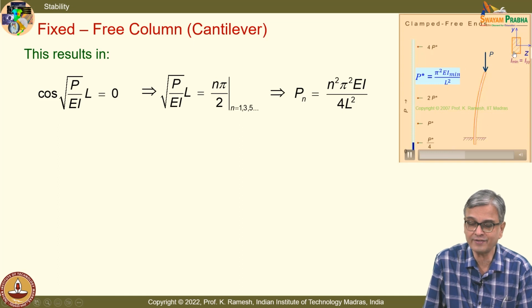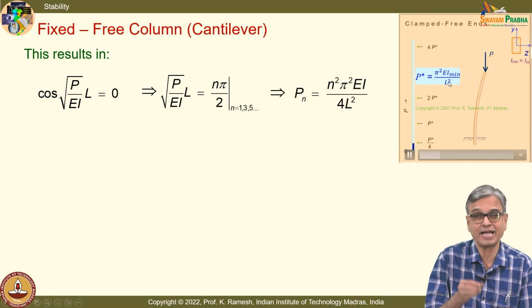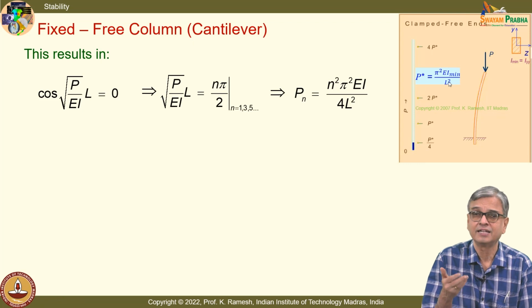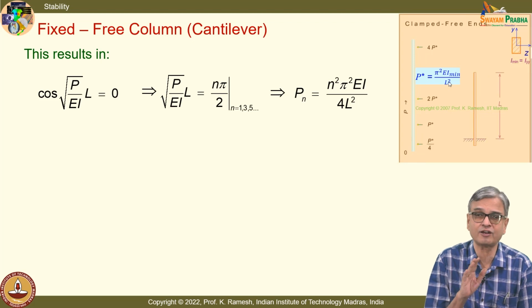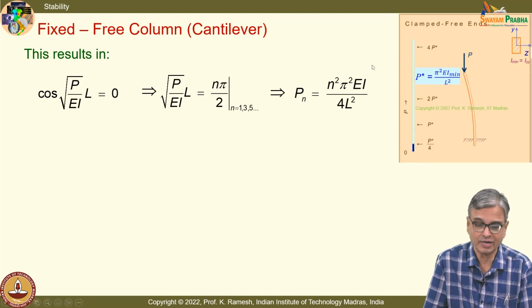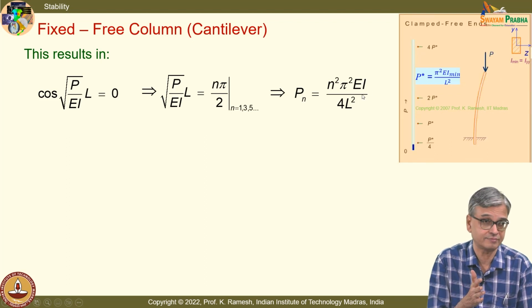And you also have a rectangular cross section, and your minimum moment of inertia is Iyy. So, explicitly in the expression it is desirable to put I minimum. If I have a circular cross section, I minimum is the same as I at any one of the diagonals. But if you take a non-circular cross section, you will have to understand that for buckling or the critical load you should look at the least value.